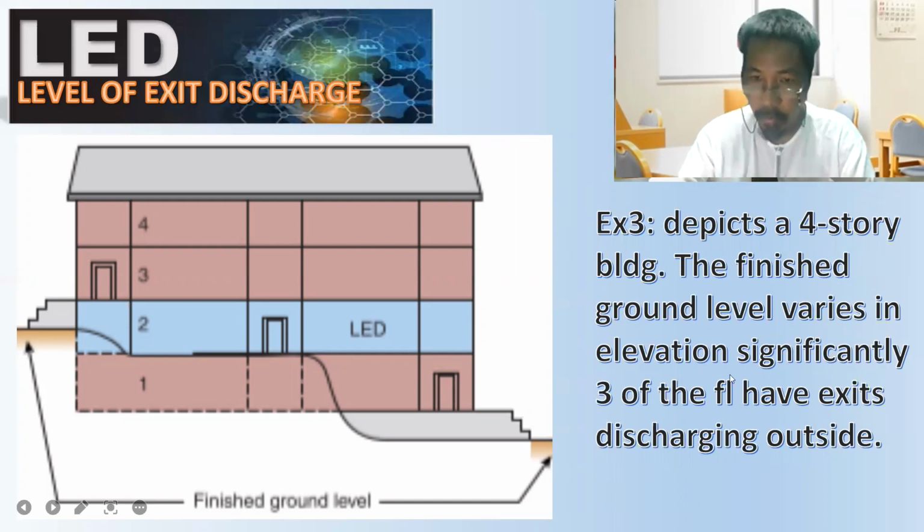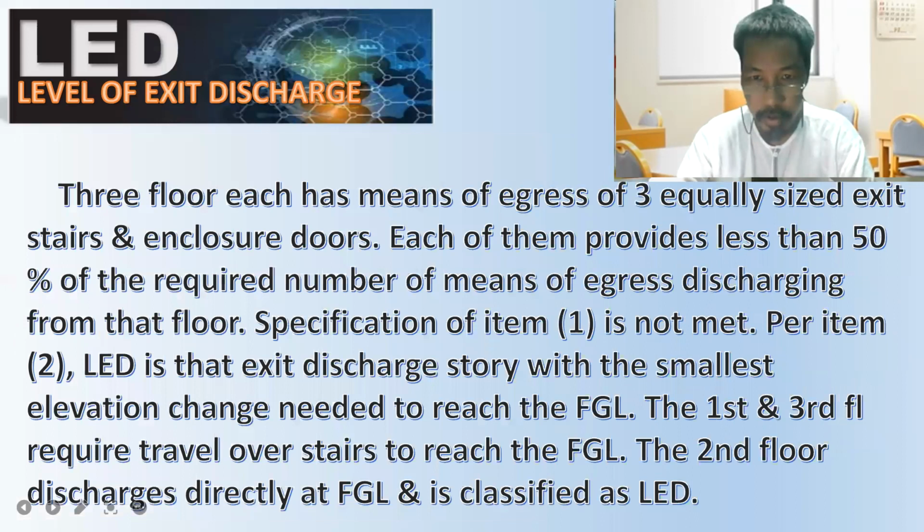So therefore, we can choose the second floor because it is discharging directly at the finished ground level and therefore must be classified as the level of exit discharge, unlike the first and third floor that require travel over stairs to reach the ground level.